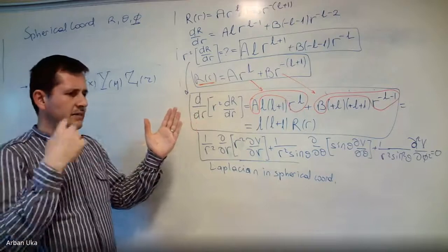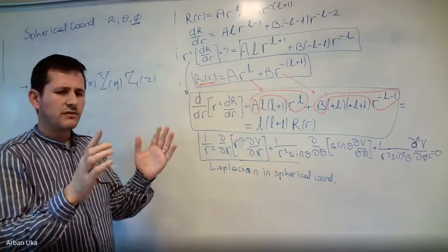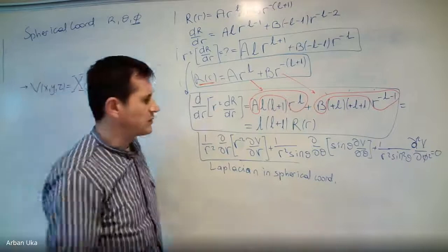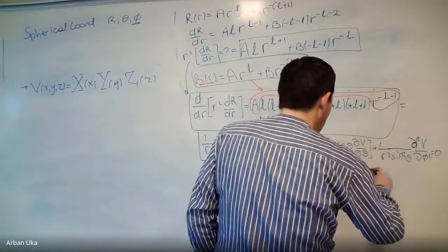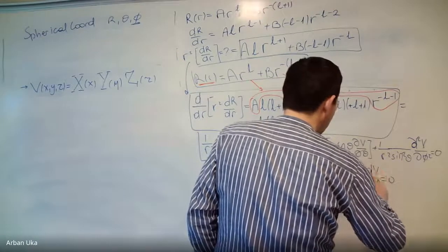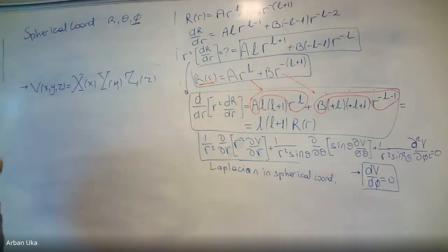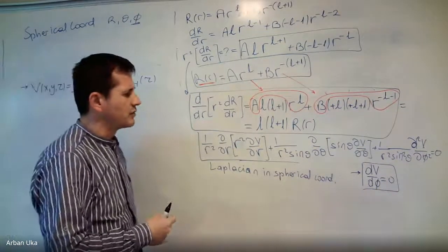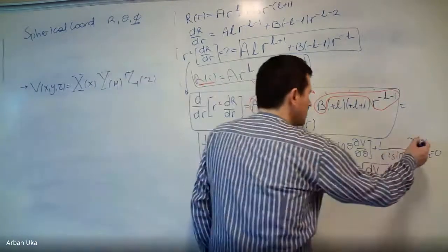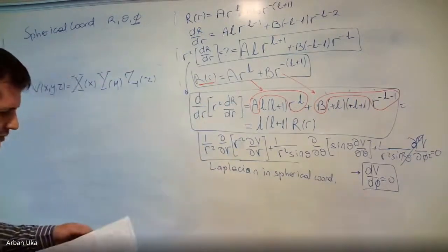This means that there is a symmetry, azimuthal symmetry, which means that the values transmitted by this antenna will be independent of phi. So here, we may assume that the derivative of the potential with respect to the angle phi is 0. We better assume this because in most cases, most of the different configurations observe the symmetry. This means that the third term is cancelled out.